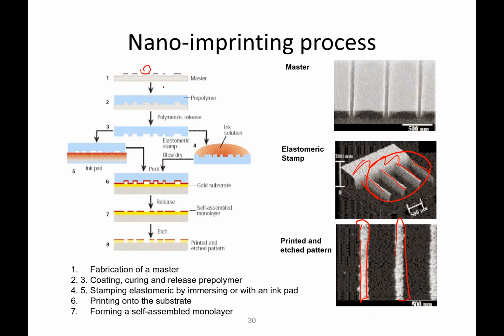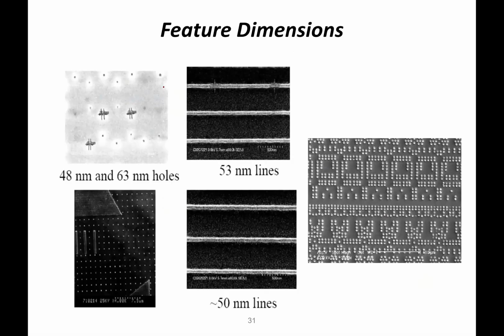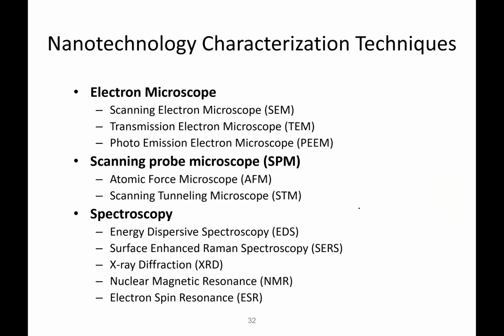Those images can be damaged, and the particles can be transferred and repeatedly generate defects. So that is the issue of nano imprinting. But the concept is pretty good, right? You can easily develop these types of patterns, but like I said, defects can be the problem.